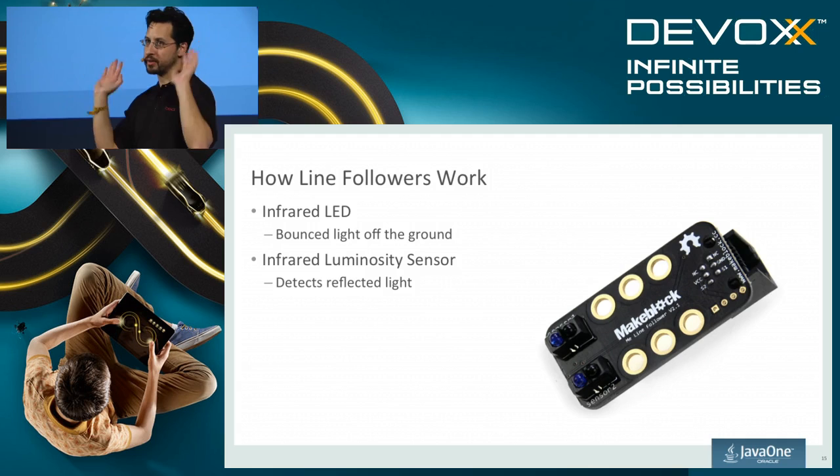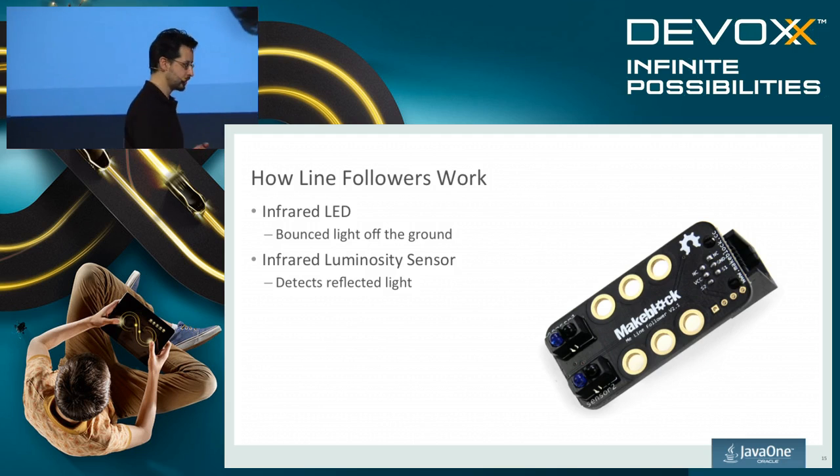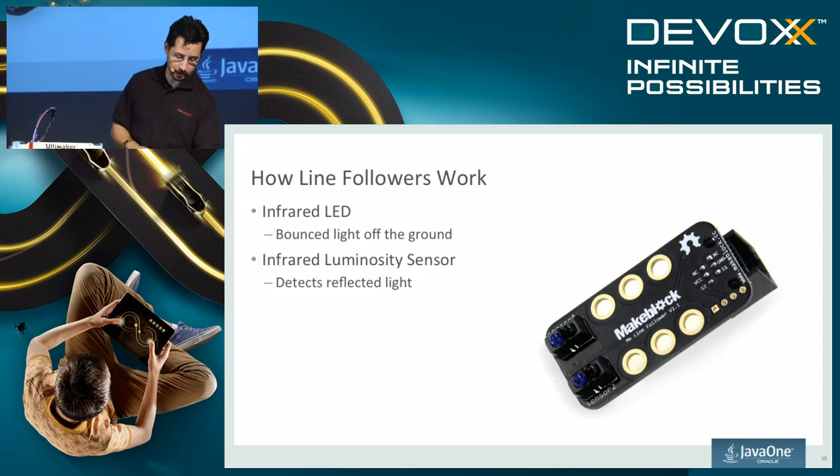If it's two white lines, well, we're somewhere really bad. We don't really know what to do, so I think the algorithm just kind of ignores that. But with two sensors, you can more easily follow a line. If you had a single line sensor when you went off, it'd be harder to tell whether you were off on the left or the right edge. So this makes it much easier to chase the line and go fairly quickly.